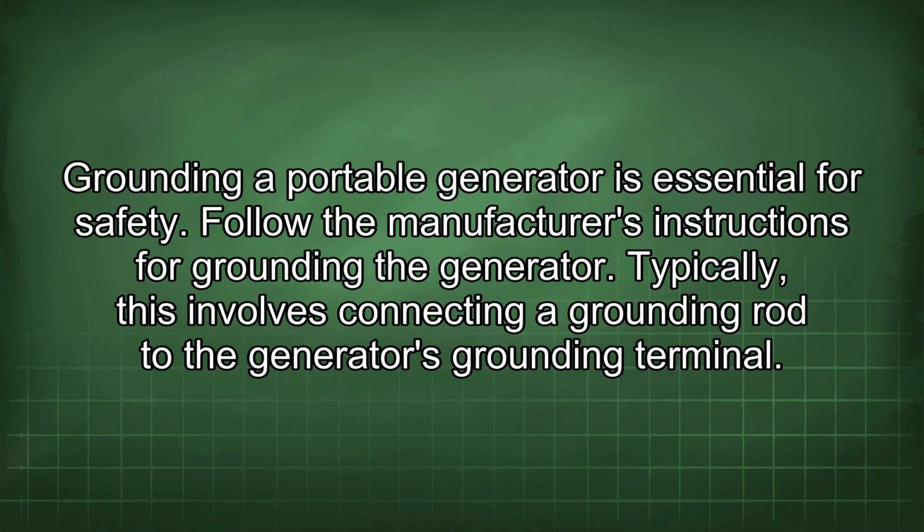Grounding a portable generator is essential for safety. Follow the manufacturer's instructions for grounding the generator. Typically, this involves connecting a grounding rod to the generator's grounding terminal.